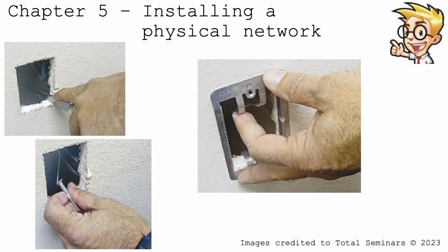Okay, so running cable and making a cable drop is not easy work. It takes a lot of physical labor and usually multiple people. So you would have to cut a hole in the wall, like a square. You would have to get a wire through the wall. Look at this pin, this screw that's used, and they pull the wire through, and that way they know that it's a good drop and you can push the cable through later. Okay, they put the faceplate on,